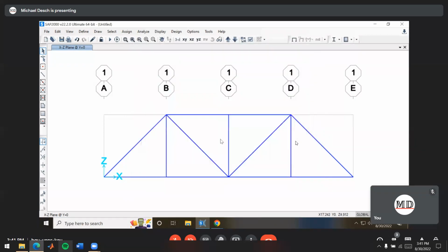And we'll press OK. So that's imported it, but now we need to assign it to all of the members here. So we can select all the members here. It's just like the AutoCAD rules for selecting here. Clicking and dragging right will select everything that is fully within the selection box. And if you click and drag left, that selects everything the selection box touches. You'll notice we've got these kind of dashes along the members here and these X's on the nodes here. So that means it's selected.